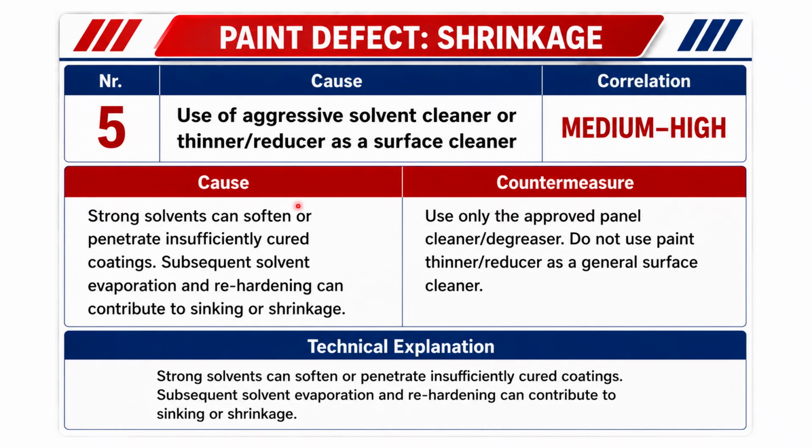The number five probable cause could be use of aggressive solvent cleaner or thinner or reducer as a surface cleaner. Strong solvents can soften or penetrate insufficiently cured coatings.